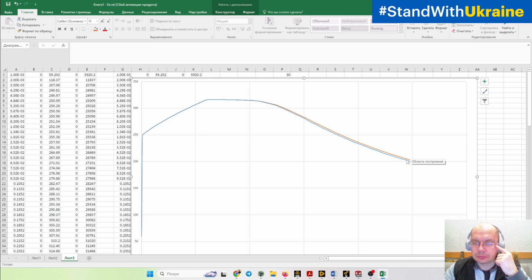It will not give a chance to use this type of data. And when you start to look at why, you will understand that the data which you obtain from the real tests are not real strain and real stress. It's engineering stress and strain. So you need to recalculate it, you need to input it, and only then maybe you have a good solution.